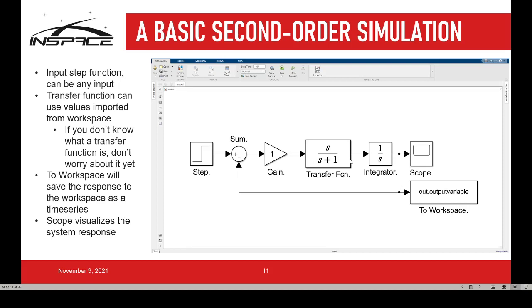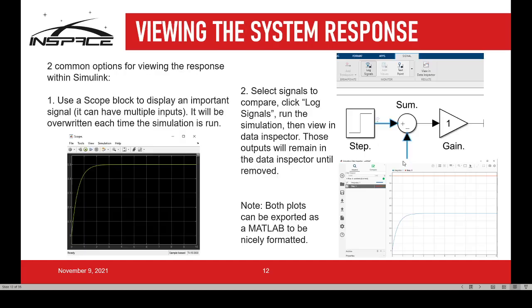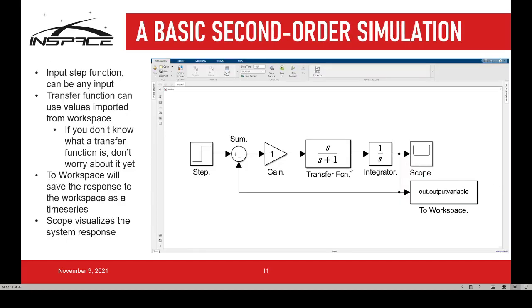Okay, integrator. This one just integrates. It's a transfer function of 1 over s. But an easier way to describe this physically is the numbers come around, and it kind of holds your numbers here, and then it adds up the previous signal that's coming in. It's integrating. It's adding it up over time. And then this all gets put into 2 different outputs.